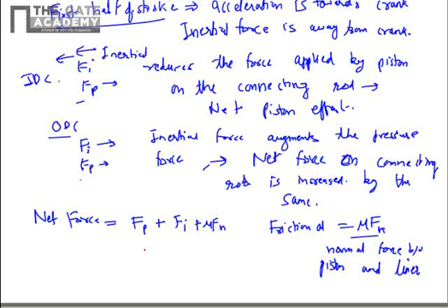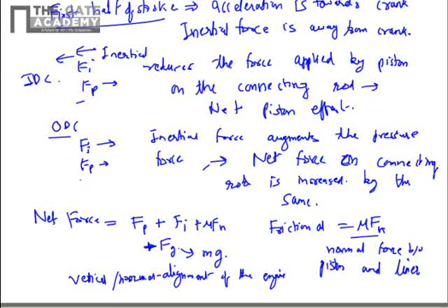And then finally, if the cylinder is vertical, the gravity force plus Fg, gravity force, which is normally equal to mg, mass of the piston and gravity. So the direction you can determine based on the alignment of the engine, vertical or horizontal. Based on that, this force will be determined. So this net force we will be using for our next step for determining the thrust on the connecting rod.